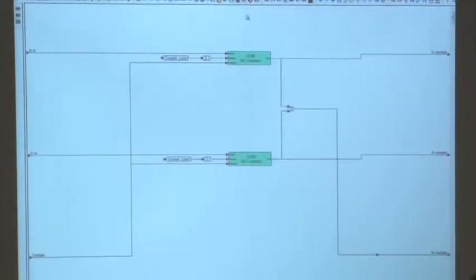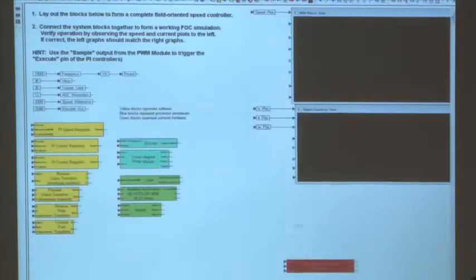I've got 2 simultaneously sampled 12-bit A to D converters. And then I take those samples, add them together and take the negative, and that generates my third current sample, as shown right here. Now I've got my 3 current samples.